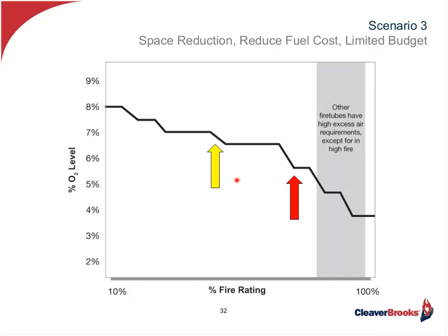We didn't match the boiler to the load. The other thing is it could have a linkage system, an air-fuel control system that is not consistent. It does not repeat properly. It's got slip. It's got hysteresis. It's got problems. So our excess air level is rising.